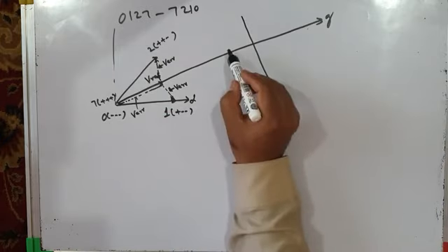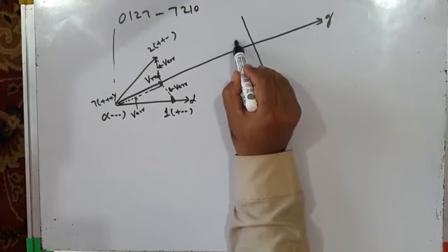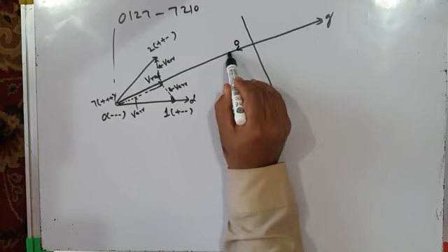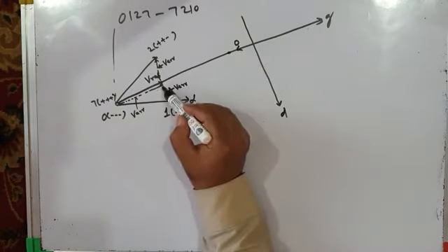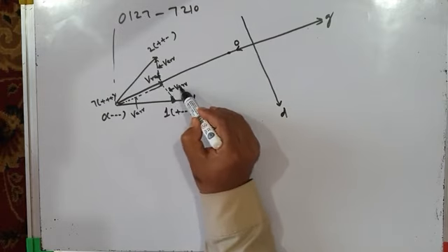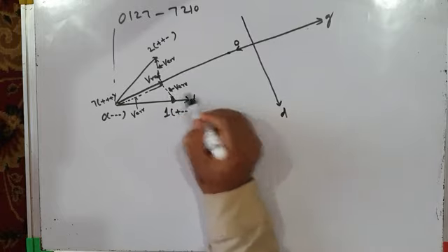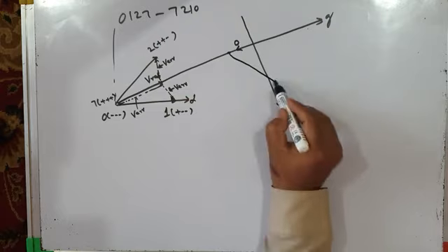Its integration will give us stator flux ripple when null vector 0 is applied, which will grow in this direction. It will have maximum negative values somewhere here. When active vector 1 is applied and this error voltage vector is integrated, it will give us stator flux ripple, which will grow in this direction, parallel to this.